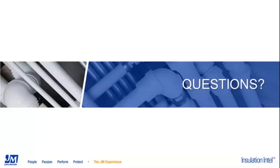Great, thank you, Kim. Great question. From the high level, absolutely jacketing can be installed without the rivets or screws. Banding can be used. For preventing the water intrusion, the overlap should be installed such that it's pointing downwards. Also, if it's an outside situation, you might want to consider the wind direction so that in a driving rain situation, it's not driving the water in there. Yes, there are sealants that can be used, and I recommend it to be used when installing jacketing.